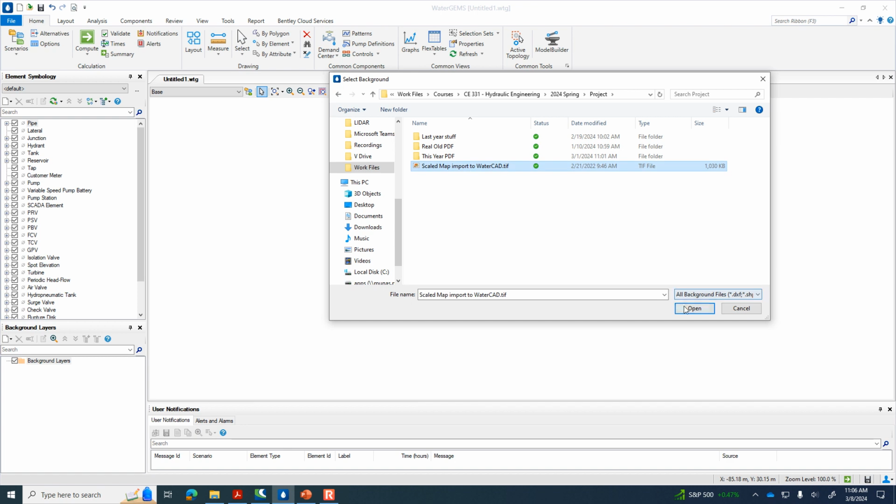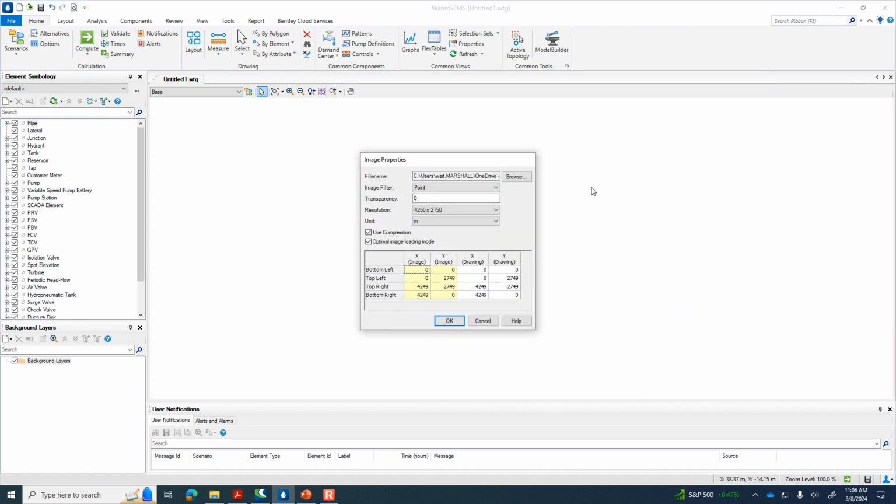So when you select the file and click on Open, it's going to come to an image importing menu, where you're given options related to scaling. It's asking where the bottom left part of the image should be set in the program's coordinate system. Down here at the bottom, if you move your cursor around, the cursor has locations in terms of its x value and y value, so x and y coordinates. And so here, when you import the image, you're just telling it where to put the image in your system's coordinates. And you can just use the default. There's nothing that needs to be changed there.